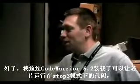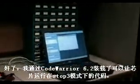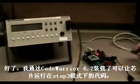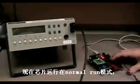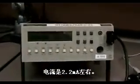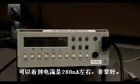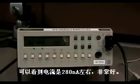Alright, we're back. So far, I've loaded some code that all it's going to do is put this part in stop 3, and we're going to measure the current when the part's actually in stop. I've already loaded that with my CodeWarrior 6.2. It's in a run mode right now. Obviously not doing much because we're only at 2.2 milliamps. As soon as I push my PTA2 here, we're going to go into stop 3. So as you can see, we're at about 280 nanoamps for a stop 3. That's a very good number there.